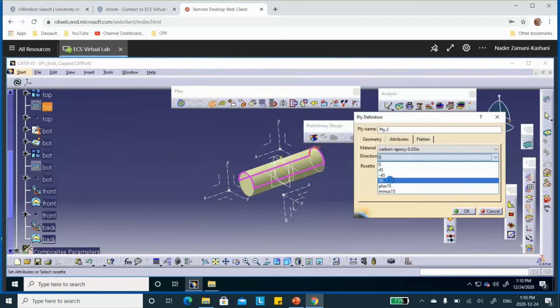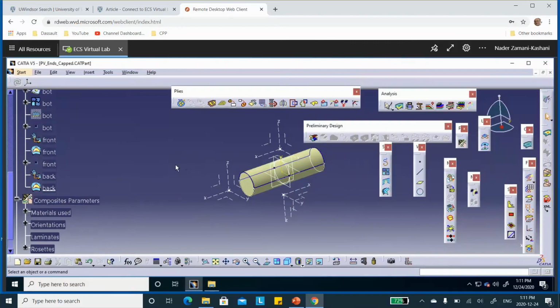However, I made a mistake in the other video segment, the earlier one. I forgot to change this to the cured thickness of 0.15. Remember, 90 degrees goes with cured thickness of 0.15. So I ended up correcting it and took some time. Okay, so that's good. You can always check, make sure this is right.